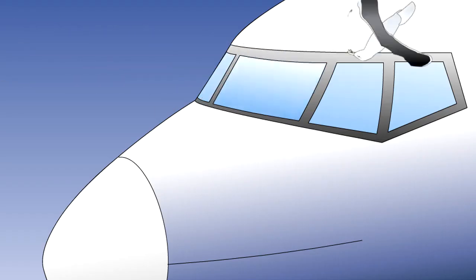The aircraft must be capable of continued safe flight and landing after impact with a 4-pound or 2-kilogram bird when the velocity of the aircraft is equal to its design cruise speed, VC, at sea level, or 0.85 VC at 8,000 feet, whichever is the most critical. In other words, the windscreen must be able to withstand this impact without penetration.